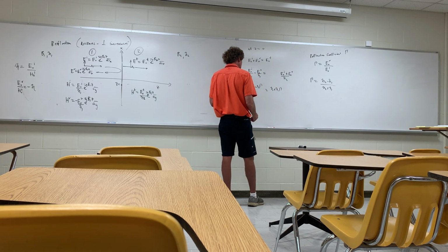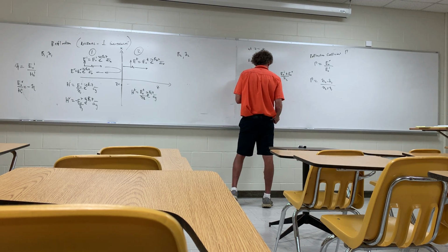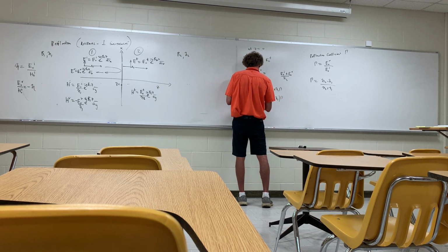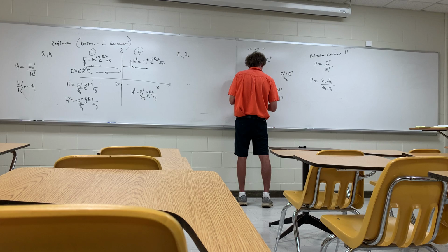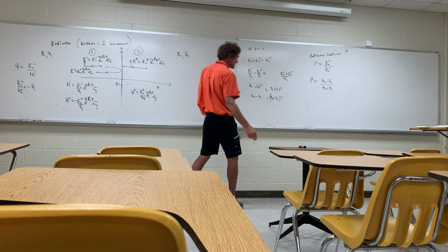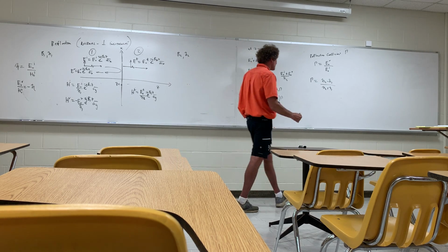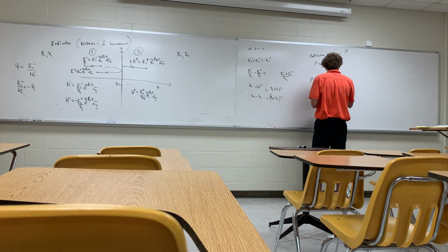Then you gather the reflection coefficient terms, and you have eta 2 plus eta 1 times the reflection coefficient is equal to eta 2 minus eta 1, and from there it's pretty obvious. You just divide by eta 2 plus eta 1, and you have what I put there. This is called the reflection coefficient, and again, it's equal to E naught reflected over E naught incident.